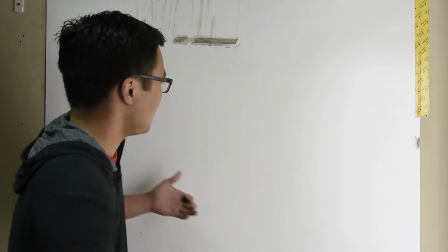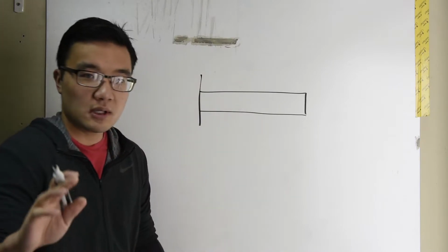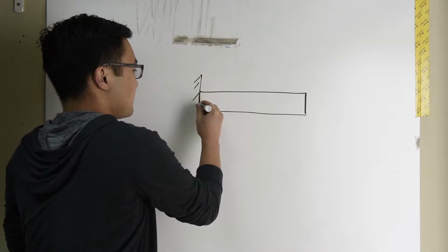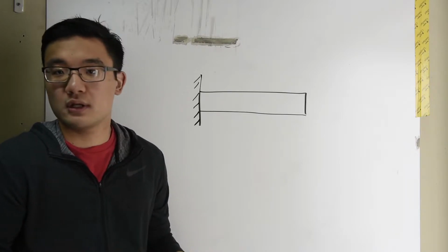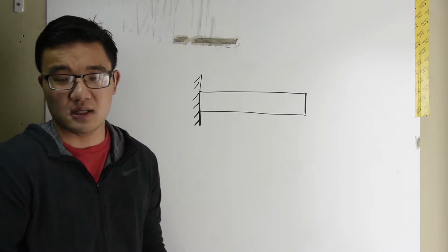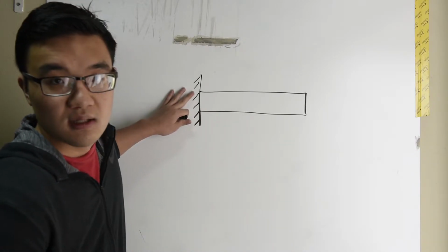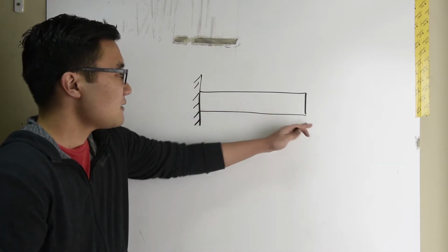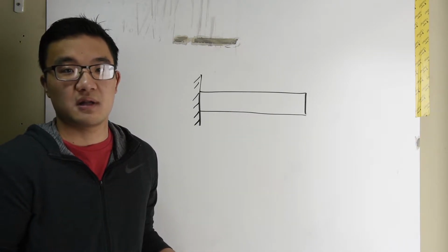Now, if I draw, again, my favorite example, the cantilever beam, let's do that. I want to mention something real fast here. This cantilever beam is not my favorite example for no reason. In fact, if you're going to simulate any sort of wing loading on the plane, you can typically assume that the wing is essentially a cantilever beam because it's fixed by the fuselage. Imagine this side to be the fuselage, and it's free at the wingtip, right? This is a very simple representation of how the actual wing is mounted onto the body of the plane.